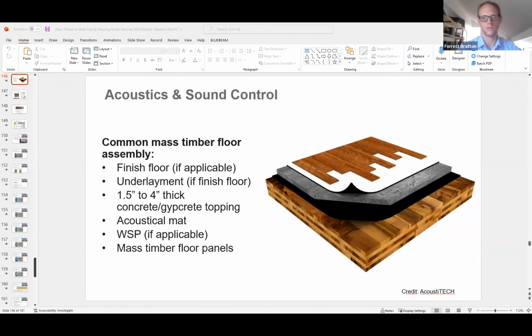I can describe it. Basically, a multi-layer buildup, including Acoustimat and a layer of insulation and a couple layers of dense board. It was a more robust system than you're used to seeing on top of a floor, where in a truss system you might only have your decking and then gypcrete and then finish. And by the time you've got that and you've got the cavity and you've got ceiling below, you have a decent sound barrier, something like this.